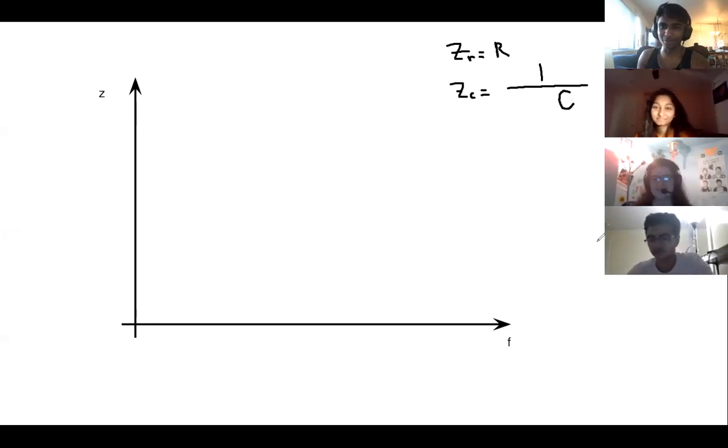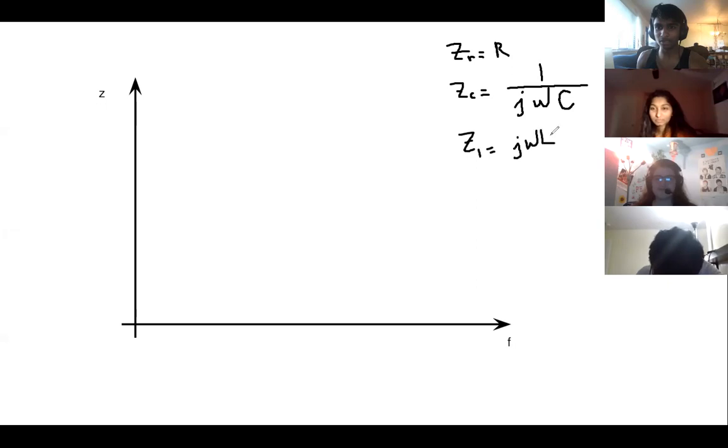And we're talking about frequency. Do you think frequency goes in here somewhere? Maybe in this gap? Definitely. Oh, the period. Yes. So I'll use omega to represent that. And then when we're working with complex numbers, we just like to throw in j's everywhere, right? So that's it. Oh, I vaguely remember this. Yes. So this is how a capacitor behaves at different frequencies for a given impedance. Okay, whatever. Inductor, I'll just give it to you because you probably didn't talk about it in ISIM. It's j omega L. It's like the opposite.